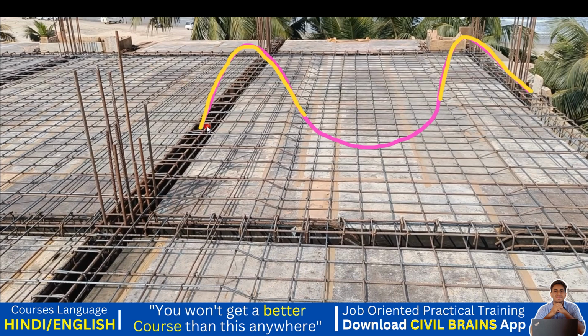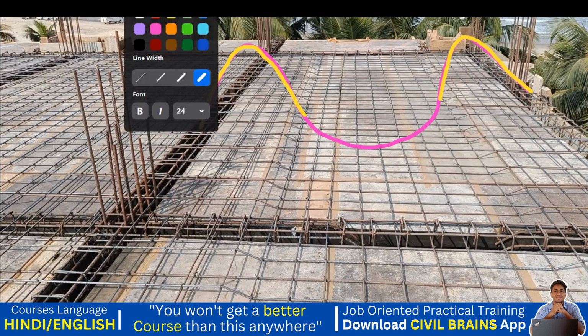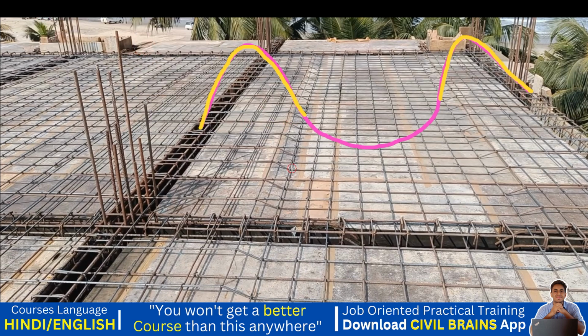Now since my slab was trying to lift up, what I should have done is provide the top reinforcement, right? Because even in the beam we did the same thing. If your beam was trying to lift up, we wanted to provide the top reinforcement. That is why we had provided the bar straight, you remember, up to here we have provided the bottom steel. But since from this point my slab was trying to lift up, for the same bar I gave a crank. Crank is nothing but a bend, and I have taken the bar to the top.